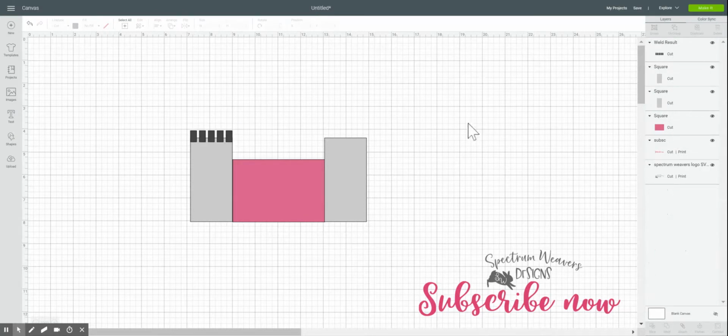Now once you have welded a shape, you cannot unweld that by any other method than using this back button. And once you've moved forward in your design, that's not something you're going to be able to do. You're not going to want to back out through all of your design and erase all of what you've done. So once you've welded it, that's it. It is now a welded image. It's all one piece. And this will come up later on, but when I select that, you can see over here it is now one single layer. Before, each of those would have had their own individual shape over here. They're now one layer, okay?